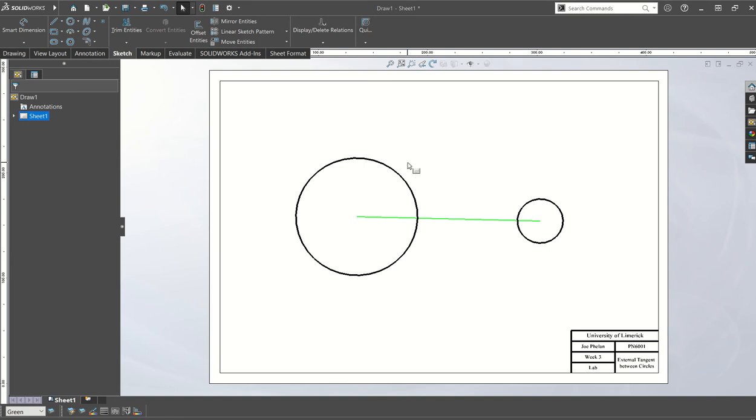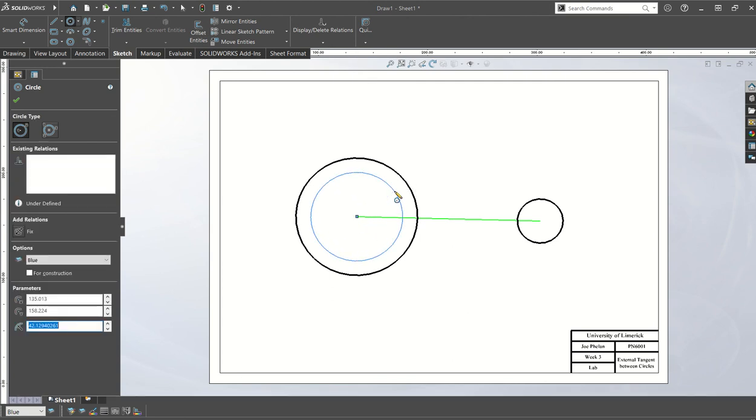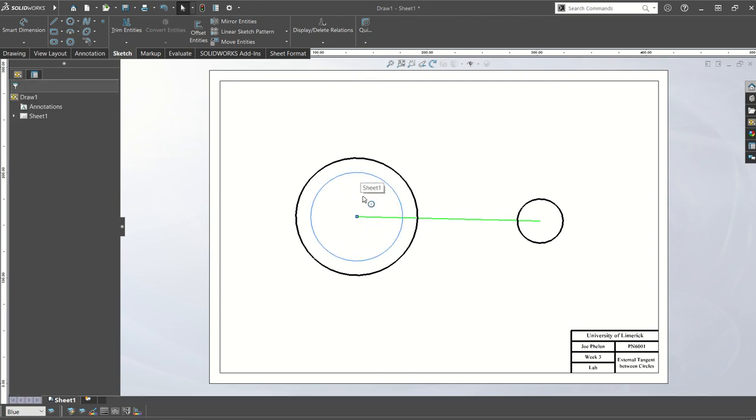And the fundamental principle that we use is we reduce the smaller circle to a point such that we take away its radius from it, and that leaves us just with a point. And we take away that very same distance from the larger circle. And one way of doing that is to first of all just draw in any circle in our larger one, because we know that this is going to now be represented in a smaller form and it's free to move.